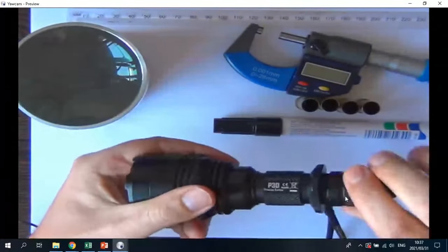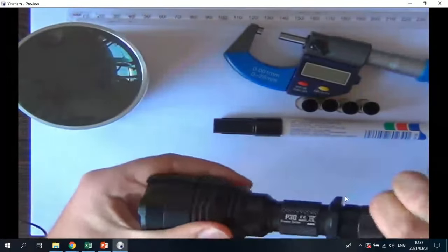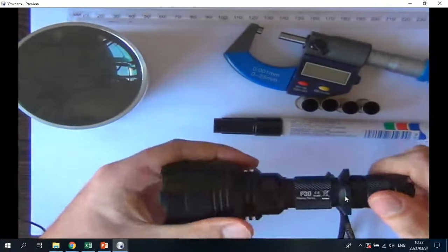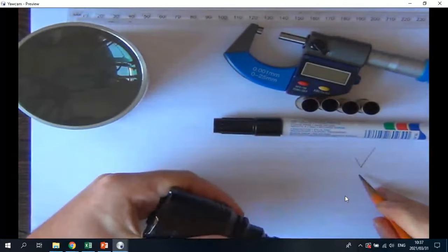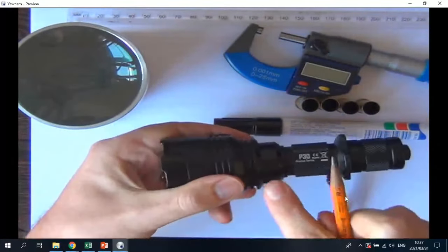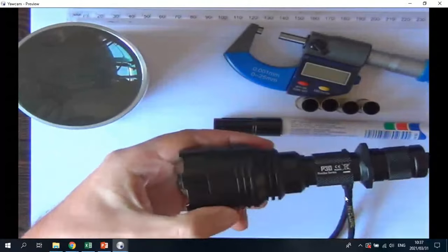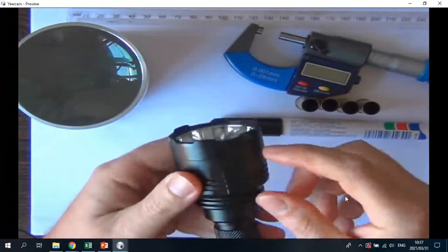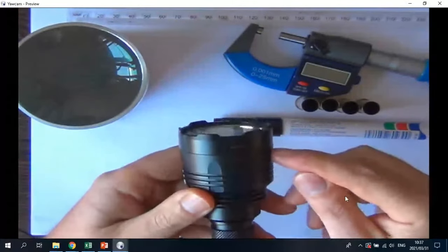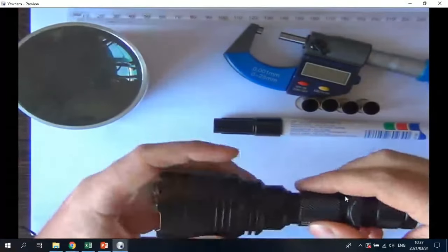So this surface will then be indicated by that first machine symbol, just the open one, that you will use to indicate the roughness of this kind of surface. You can now imagine you wouldn't necessarily want this surface to be mirror smooth, but also not too rough.